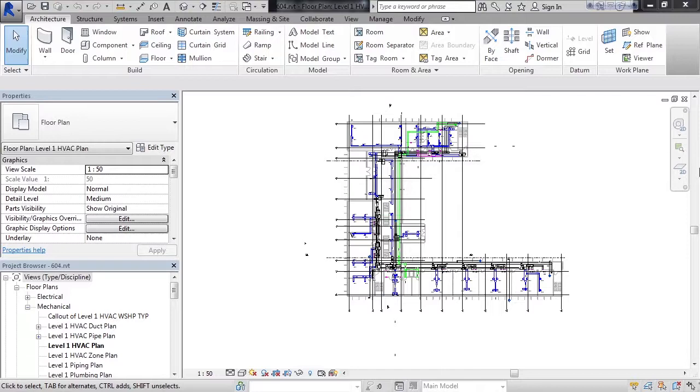In this lesson, we'll cover elevations. In our previous lesson, we looked at creating building sections, or a section in certain parts of your Revit model. Here we're going to look at creating elevations. Typically, an elevation would be used for an exterior elevation or an elevation of a different part of the building. So we'll walk through creating an elevation of an exterior face of this actual building. And then from there, we can decide what elements are on or off within the elevation.